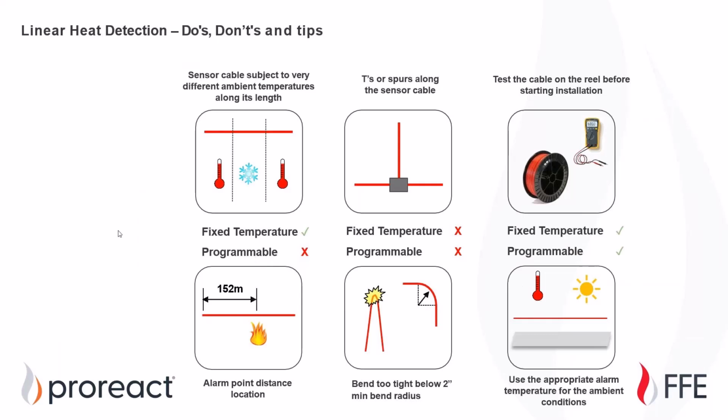And some general do's and don'ts and best practices. If the cable might be subject to very different ambient temperatures along the path, usually fixed temperature is best here. There's also leader cables that can be used if you have a hot area, then a cold area, then a hot area, and things like that. So the non-sensing cables can come in handy, especially if the controller is far from the space that's being protected.